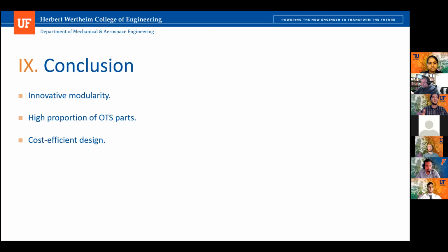So for example, if heliostats were linked by some different contraption, then you risk losing functionality in multiple heliostats at once. The module maximizes the number of heliostats in a single unit with respect to cost. It also eliminates shadowing and blocking losses, and it's easily scalable to produce a field pattern. To conclude, the proposed field layout achieves 1.73 megawatts of power input to the receiver and has an optical efficiency of 0.71. This proves that the design does indeed satisfy all the customer needs quite nicely.